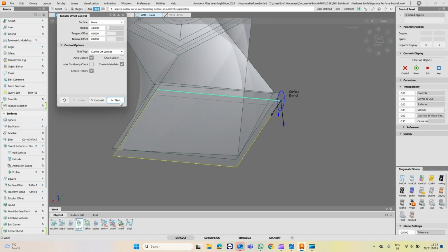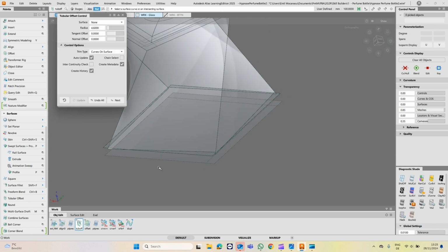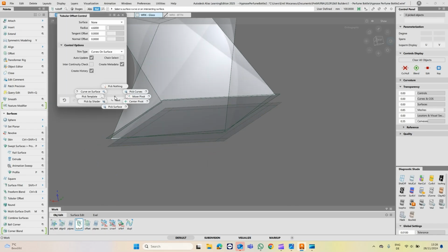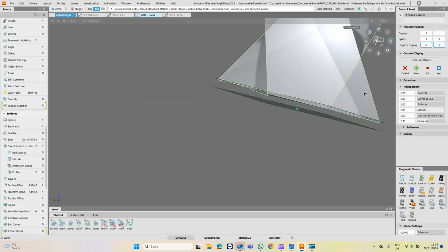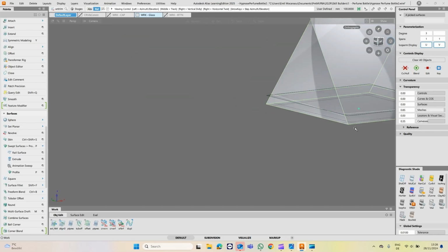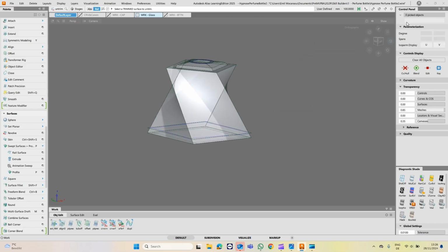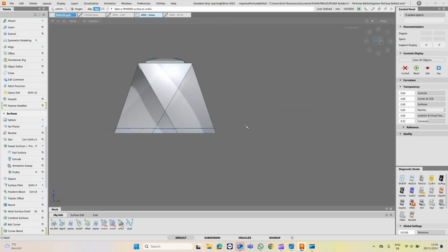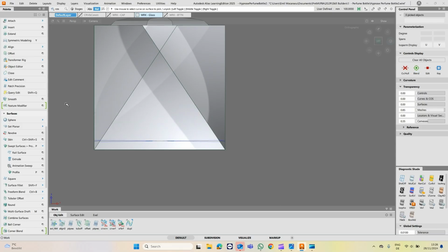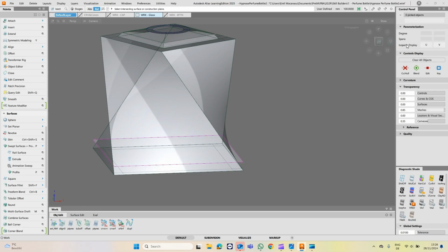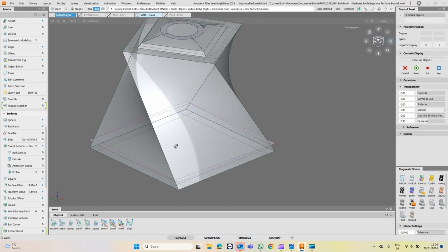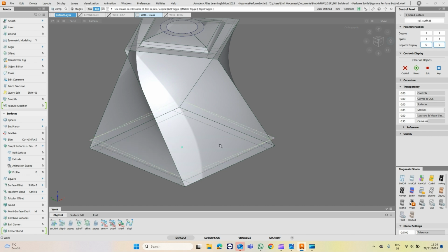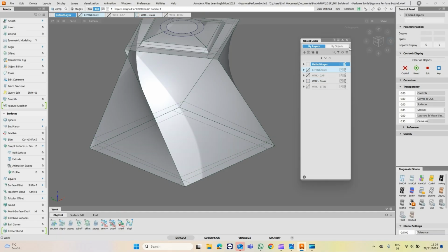Run it along there, there, there, and there. Now I'll take these surfaces. I'll untrim the last operation out. Look at it in the side view. Pick the curved surface, delete them, and then I'll intersect this with these. Now I'll template that surface. I'll hide it away or put it into this layer here.